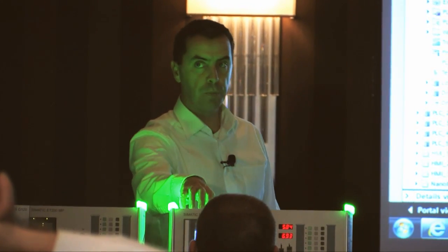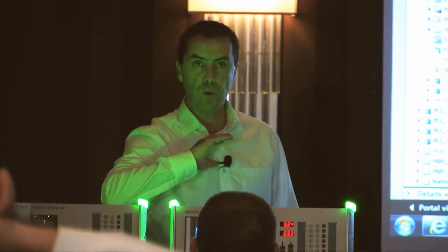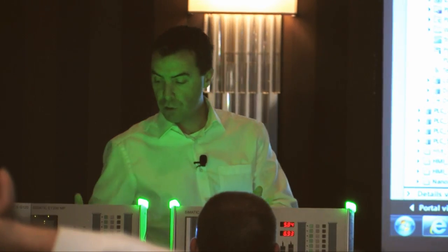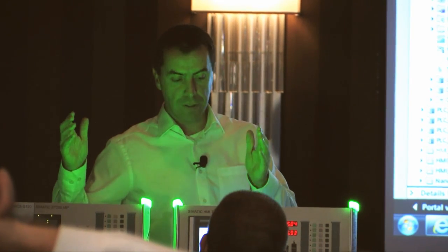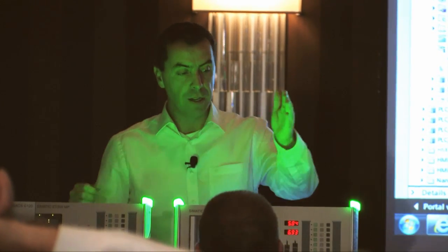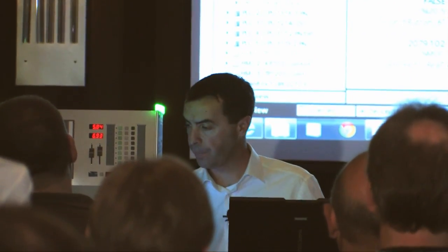An important caveat to understand with this V12 release is that this is a G120 drive, and in this particular release of V12 there is no synchronized motion; that will come in future versions. So gearing, virtual master, and synchronized motion are not in this version. But if you have simple speed applications, or even a position loop, I can do position control. Granted, it's not synchronized with other axes, but for simple position control or speed control applications, a 1500 with a G120 drive is a real sweet spot as far as setting it up, communicating to it, and handling the data. Okay, so that's getting the drive to turn.